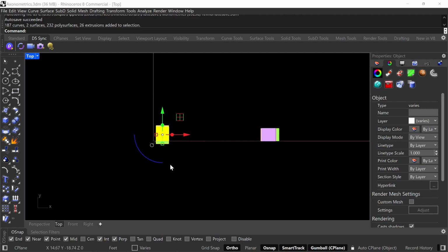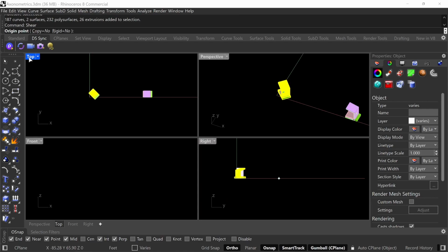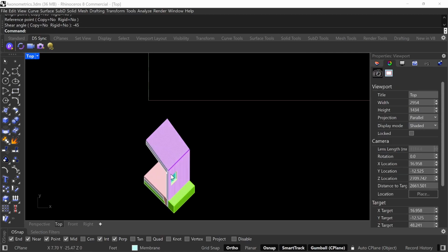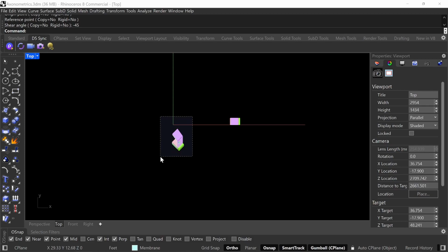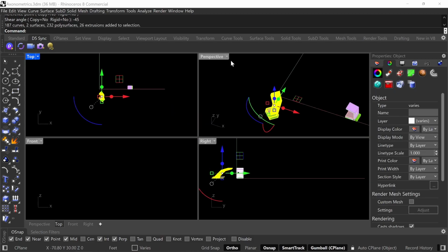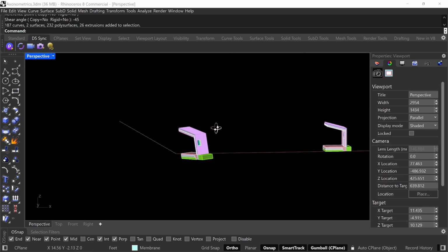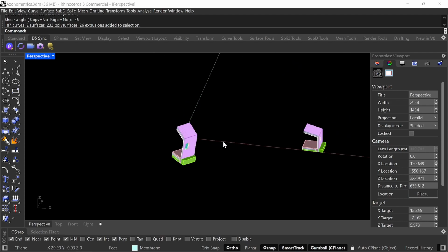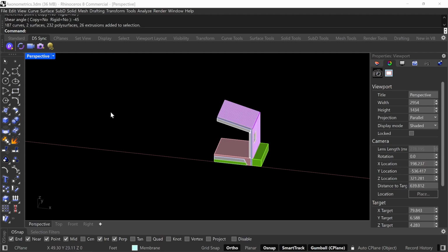Then I'm going to go here. Okay, so again, I want to rotate it 45. So that's step number one. Then I'm going to shear it. I'm going to go here on the right view and shear -45. There you go. So this is it right now. Again, if I look at this in perspective view, it's going to look super distorted. So that's it, this is done. You can't model this unless you want to re-shear it. That's why you always make a duplicate over here.